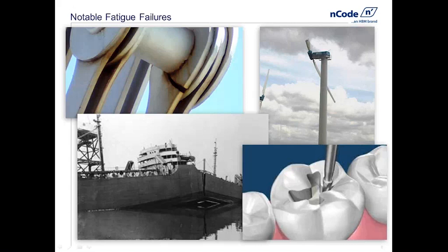In the upper left corner here, this is a steel bridge element from the Bay Bridge in Oakland, California. This is a crack that's big enough to put your hand into. This is an old bridge that you can see corrosion played some role in as well, probably. This saw cyclic loading due to a number of considerations, due to weather. So it gets hot on the top and cool on the bottom. That causes expansion and thermal stresses. Also, perhaps wind loading, traffic loading, and so on.